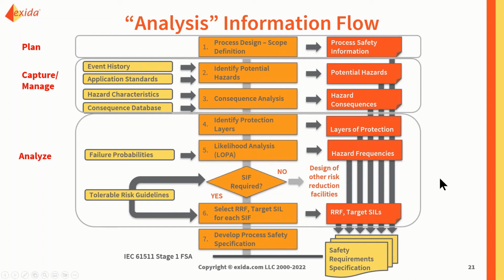And after we got all this information, specifically about the target SILs, which is the SIL level that your SIF needs to meet, then we combine it with other information. We want to have a particular document called safety requirements specifications. Specifications shouldn't be something very alien to engineering. Software engineers use specifications to build their software. Hardware engineers use them to build their hardware. Architects use them too to build architecture as well.